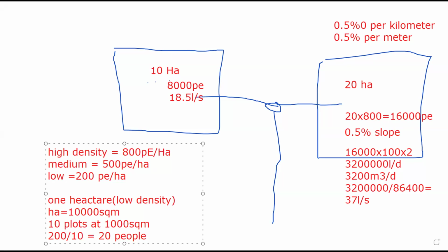So there are 3 pipe types, like we said: PVC pipe, ductile iron, and concrete pipe or asbestos, which has been banned. So the nomogram for 0.1 has a higher frequency than 0.4. So open the nomogram for 0.1, which is PVC pipe.